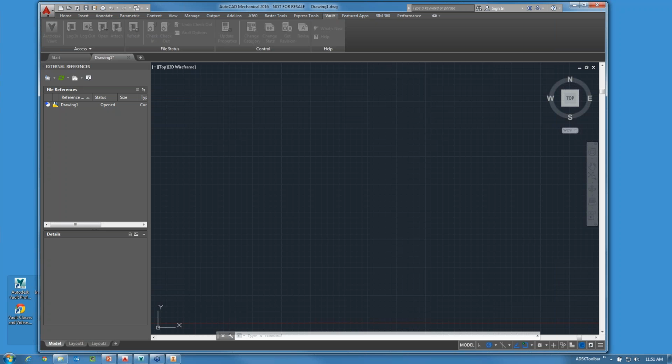How difficult is it to transfer legacy data into Vault? We have utilities to do that. If it's AutoCAD data, the way that I find it the easiest is to actually, within AutoCAD, check in folders. So typically we say, take specific product lines and move them in, or move in specific projects. But there is an autoloader that can bulk load in files. There are ways of then populating the metadata with that. In some cases you can just drag and drop into Vault, then clean it up and then copy it out and then bring it back into Vault through different iterations successfully.